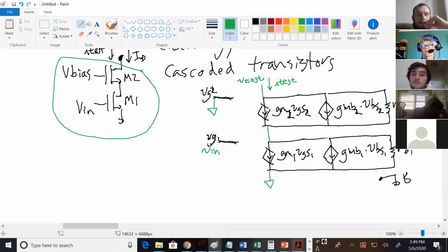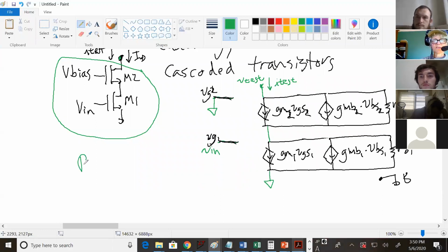Yes. So this right here is just like with the single transistor amplifier that we were looking at. This right here is considered your R out. That's the current going into here. That's actually the output of this cascaded amplifier. And so we're looking for R out.